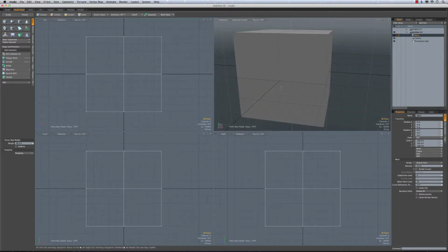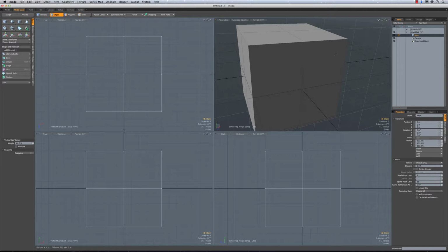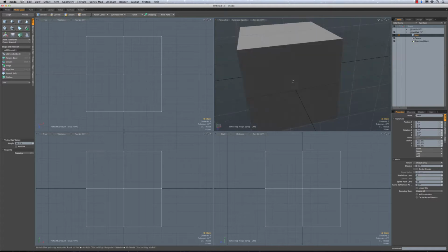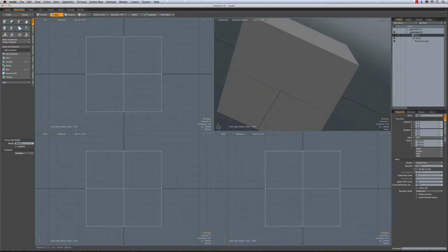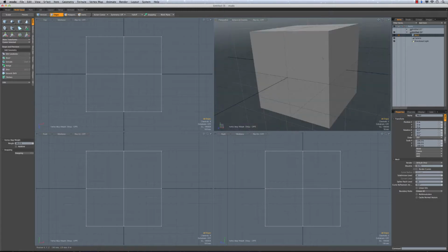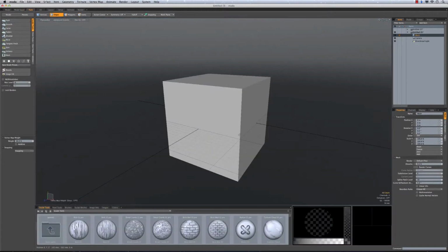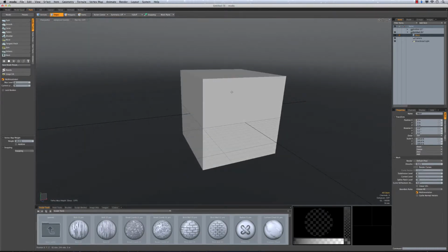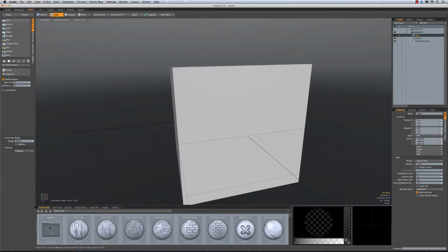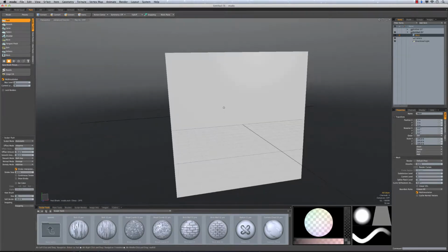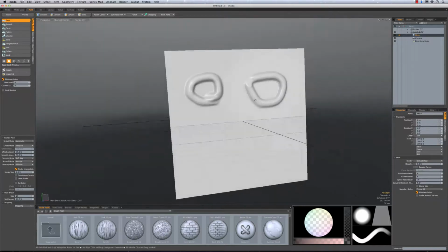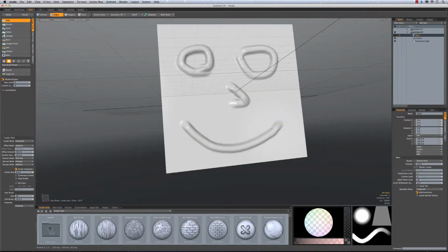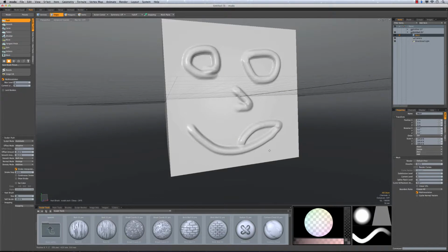And since it has a very low polygon count, it's very easy to either step back on the subdivision or bake something from that, because we're dealing with only 4 polygons on each side, so a total of 24 polys here. So just to have a look at that, let's step over real quickly to the Paint tab, and I'm going to just turn on multi-res. And then with multi-res on, you can essentially just sculpt right on top of this with no real issues. No problems here, and you can sculpt a little bit without much issue.